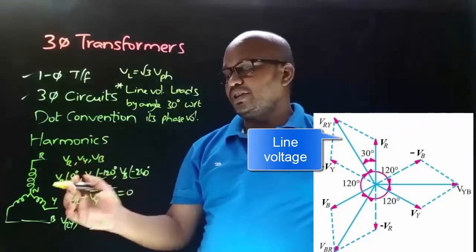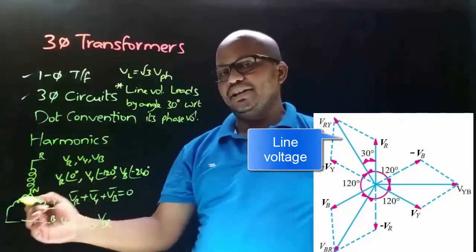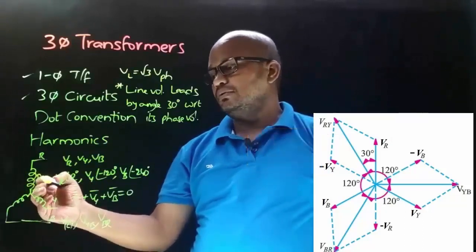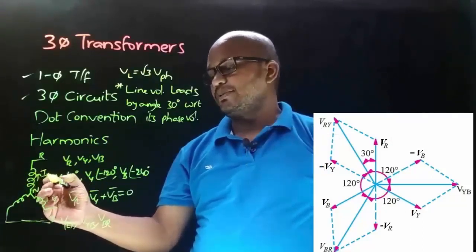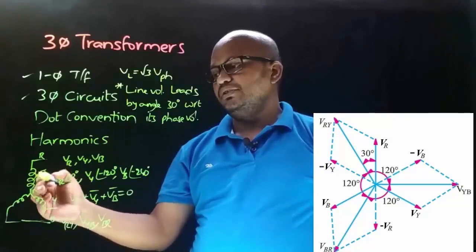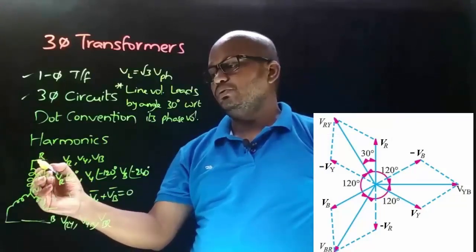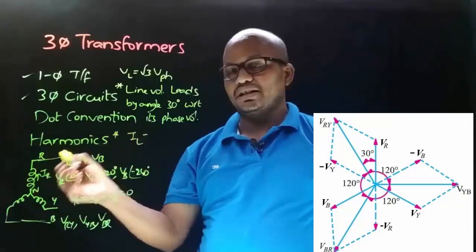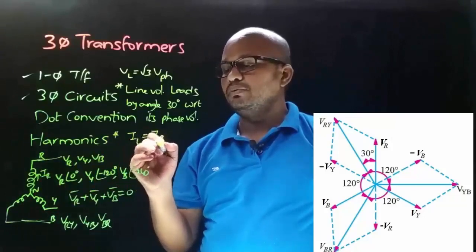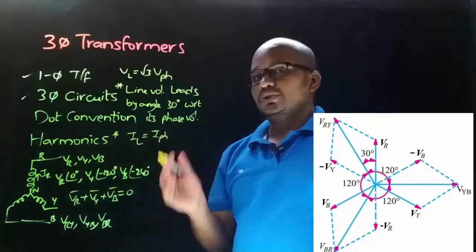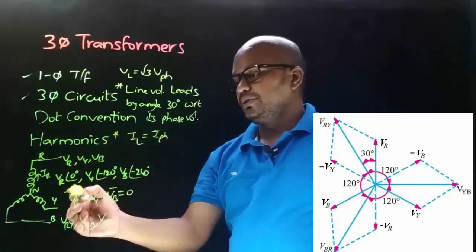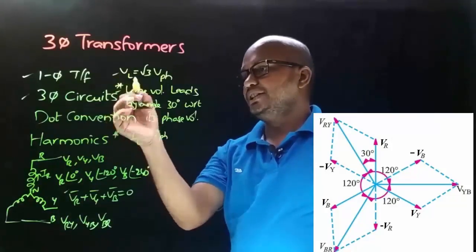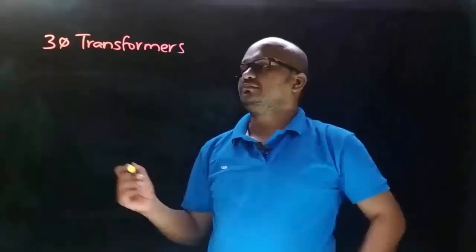This is one more important point that you must keep in mind in the case of star connection. And coming to the case of current, the current flowing in any winding is called phase current, and let us represent that with IR. If you observe, the same current will flow through this line, which means in star connection line current is equal to phase current. So these are the important relations that you must keep in mind in case of star connection.